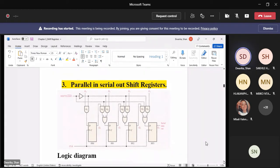Okay, so what we have here is 4 D-type flip-flops, and each one of them is clocked by a common clock pulse, and the data is out there in serial. Your inputs are D0, D1, D2, D3 going into gates 1, 2, 3, and 4.